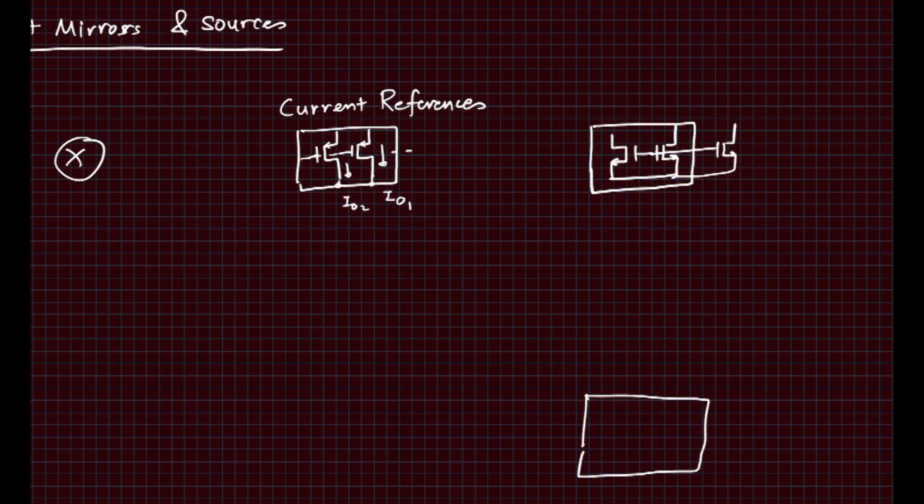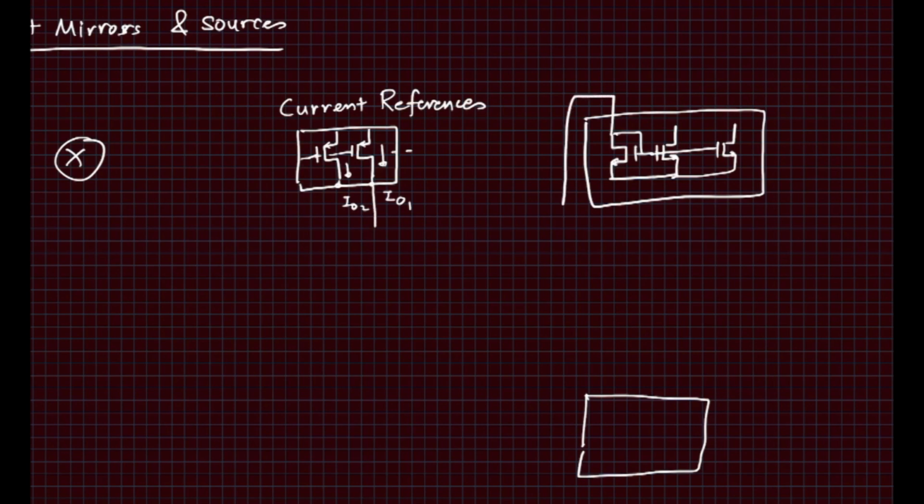In this particular current mirror that we are seeing, these transistors are next to each other. We would get this current from the reference, and this routing could be very complex depending on the layout. It could have a lot of resistance, in the kilo ohms range.